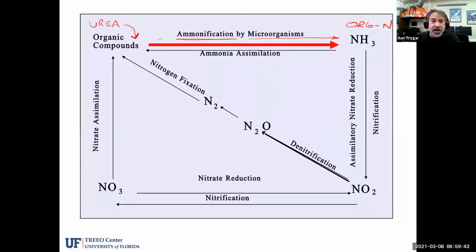Now, depending on the time in the collection system and the temperature and the amount of activity of the microorganisms, you may have more organic nitrogen than in other places. You may find that you have a lot of organic nitrogen coming in the plant in some cases, and in other cases you find you have very little. It just depends on the distance of the collection system, the length of time, any kind of bacteria action that occurs in there, and where these chemicals are making their entry point.